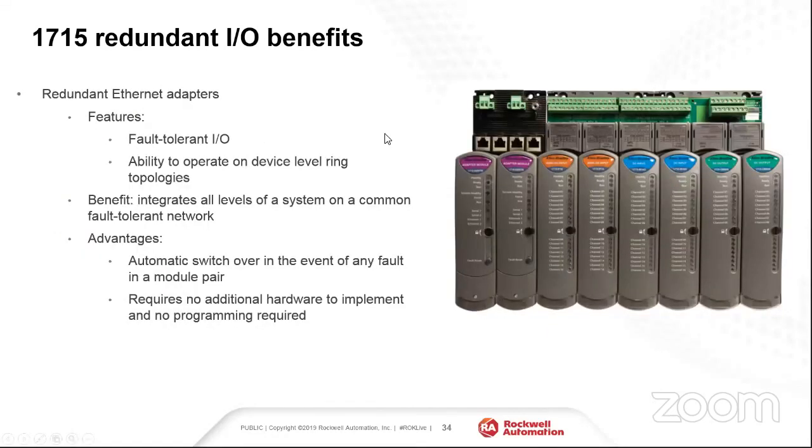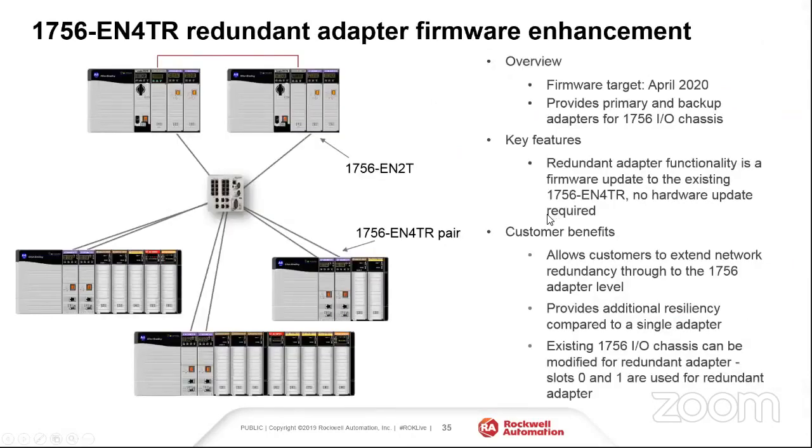So fault tolerant IO, this does provide everything in. The IP address, in most cases, what you'll see is you'll have DLR incoming connection there, jumper cable, and incoming going out. So everything is taken care of as part of the system, and this would interact as any other remote IO capability within ControlLogix. So similar to how you would interface with Point IO, ControlLogix IO, we'd have the same look and feel.